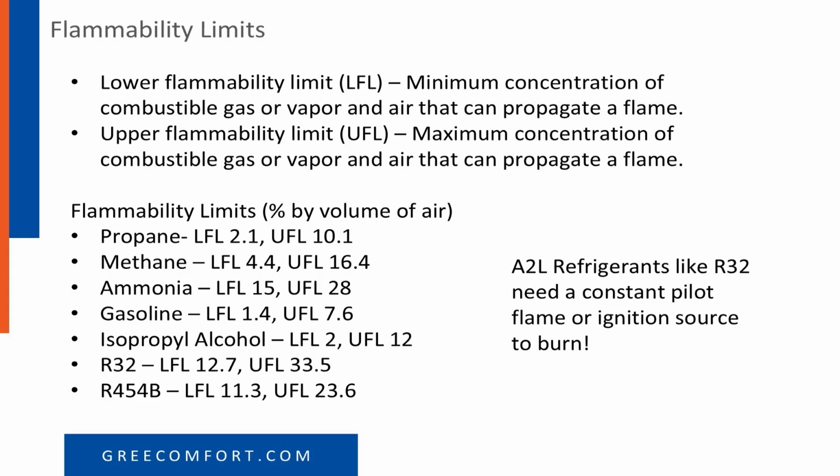limit of 7.6. Isopropyl alcohol, rubbing alcohol you put on your skin or spray on your hair with your hairspray, has a lower flammability limit of 2 and an upper of 12. So what you have to look for when we're describing these, what's the riskiest types of chemicals? Well, it's going to be the ones with the low flammability limits, right? If something goes off with an LFL of 1.4 or 2, that means it takes only a little bit of that fuel mixed with air to be flammable.